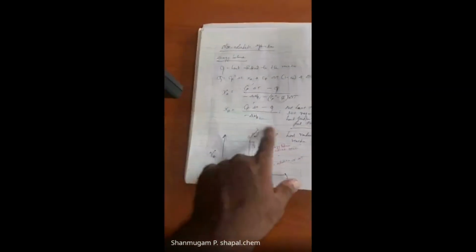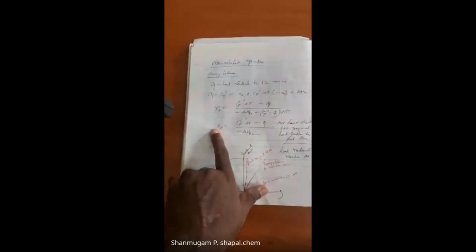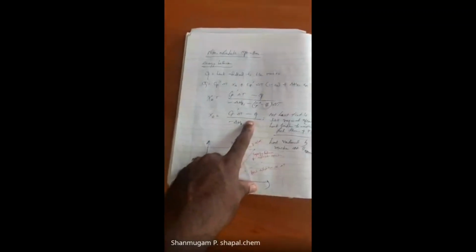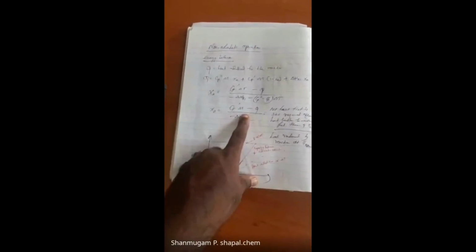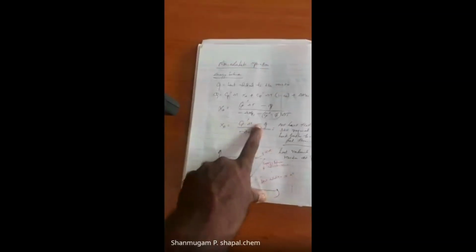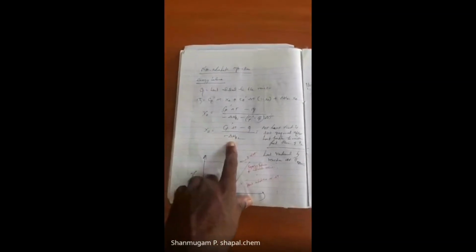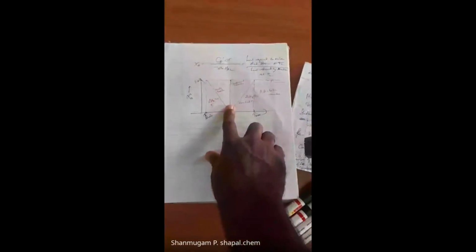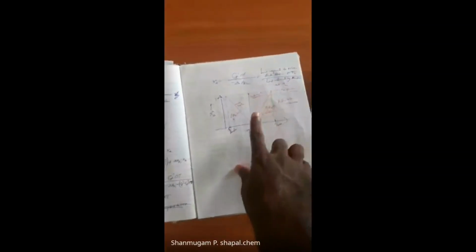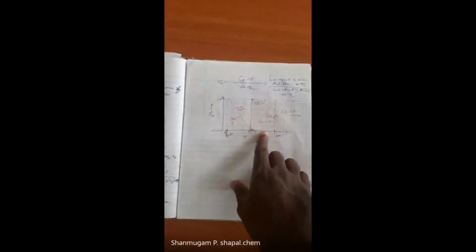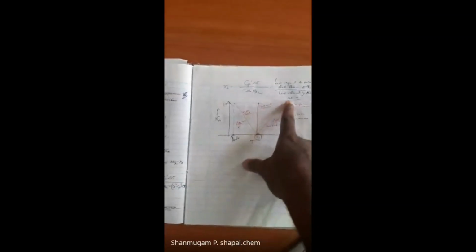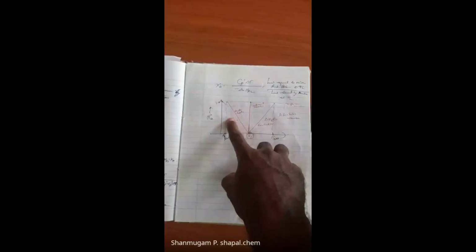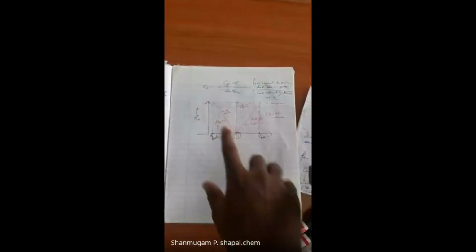And once you derive everything, you will get an expression for the conversion which depends on the net heat that is still required after the heat transfer to raise the temperature. So the actual heat required for the system, that is the net heat, divided by the heat released by the system. That is what we will explain here. And if you see in the previous case, you have an isothermal condition where no heat is being supplied in or out. So whatever heat is produced depends on delta HR, whether exothermic or endothermic. That is what is represented in the conversion versus temperature graphs.